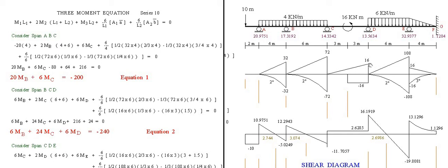Then make 18 a moment to E. The reaction at D is 18 times 6, is 108. The same is true with the uniform load down below here. The total load is 36 times 3, is 108.